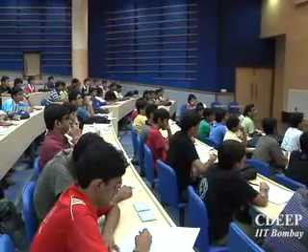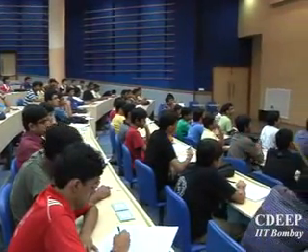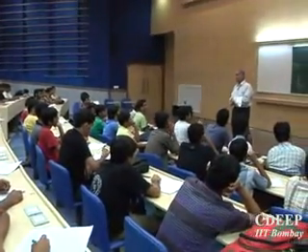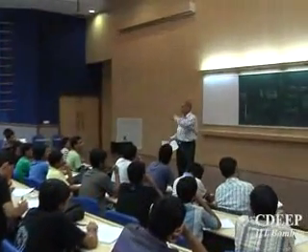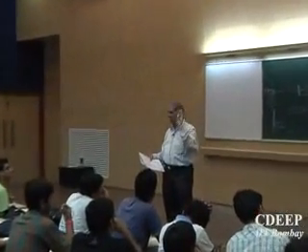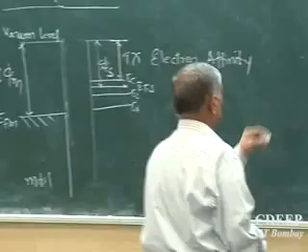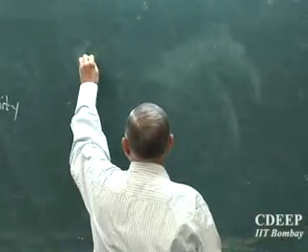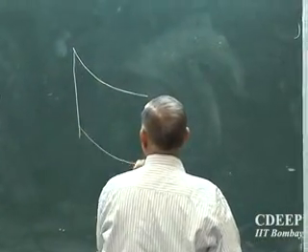Fermi levels must get aligned. And how will they get aligned? Unless electrons from the semiconductor leave and join the metal side, only then will the Fermi levels start aligning. So if I do that, I will now see something like this.